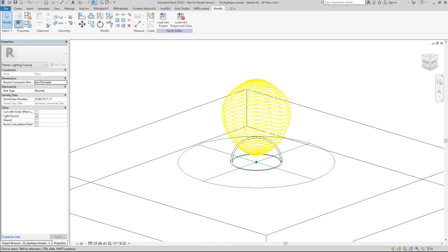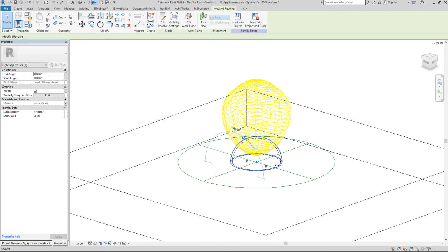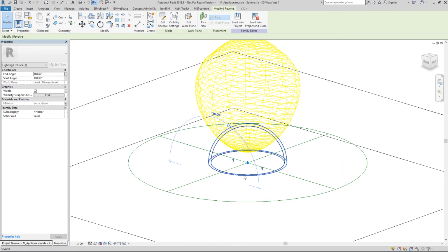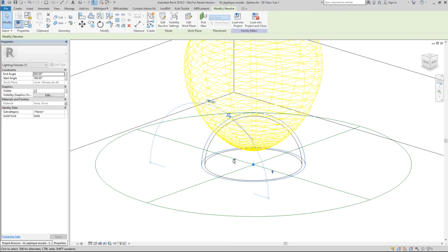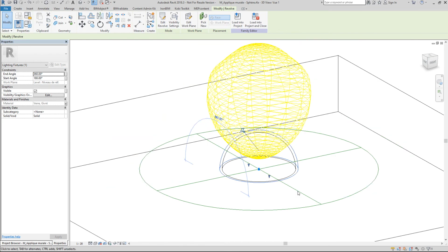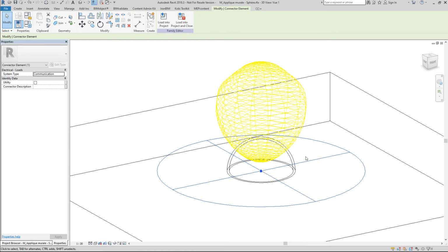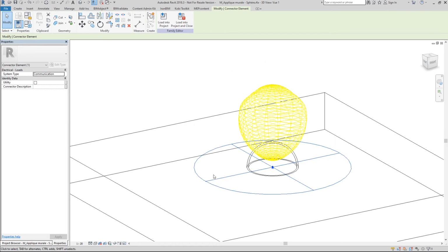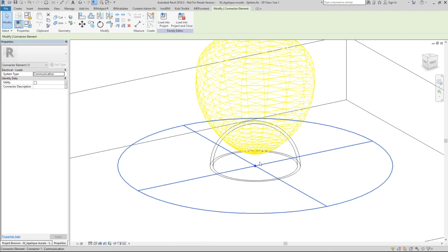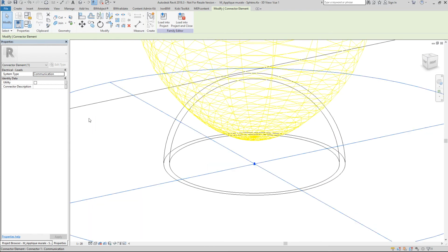Well, because oh yeah, it's a revolve. Okay, so a revolve basically is not really good to have faces, but anyway, it works. But usually we should try, in that case, maybe to do it as plane based, because if you do the connector as plane based, it will be in the middle of the plane, so it will also work. But anyway, this is okay.